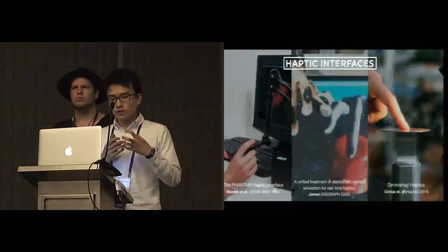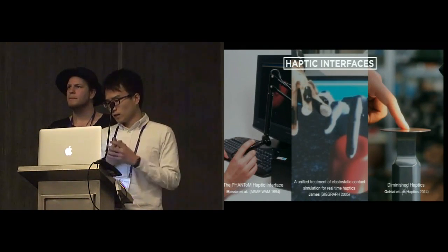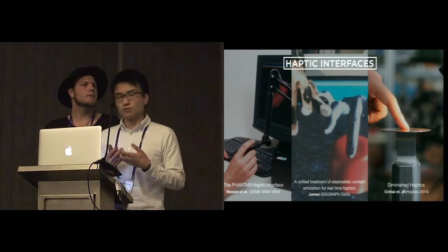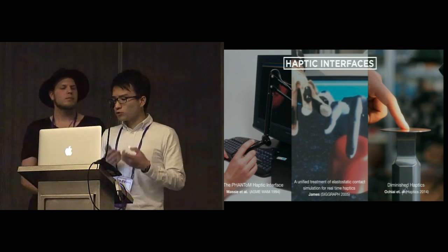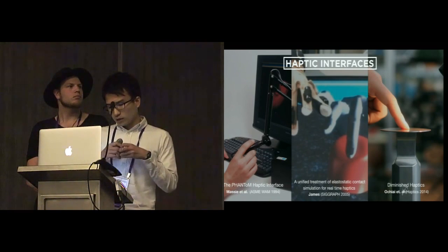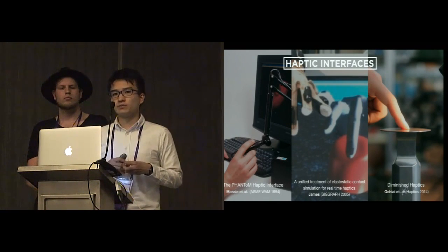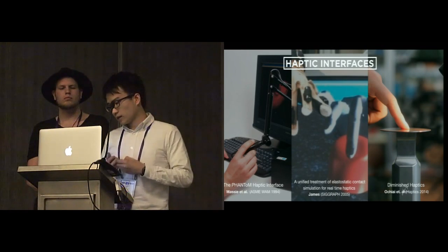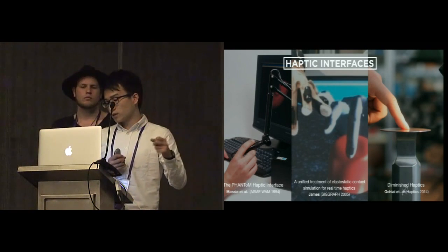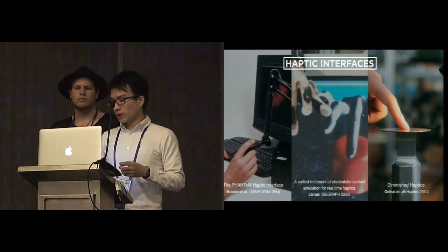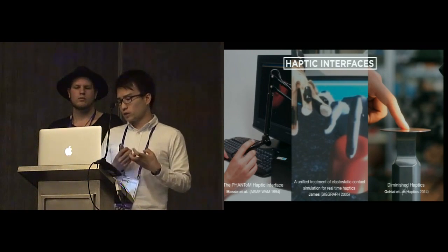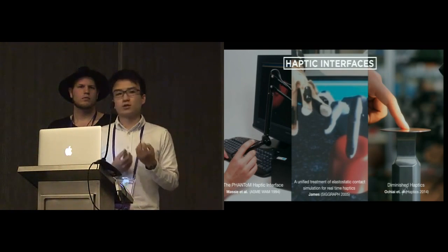To enable us to feel the rendered material properties in our hands, there have been various kinds of haptic interfaces proposed to provide actual force feedback of rendered material or shape. Although these interfaces are good at rendering actual haptic feedback to our hands, they have limited interaction capability because of their form. For example, on the left side, the Phantom limits us to interact with objects only through grabbing a pen-based device, while others are restricted to glove shape and rigid surface shape. These interfaces also lack the I/O coincidence of what users are seeing and what users are touching.